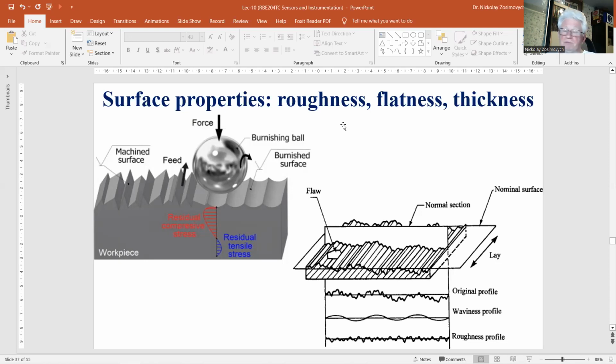Since the triangulation principle allows contact-free distance measurement, it is preeminently suitable for measuring objects having a high temperature. An example of this application is a system described for measuring the flatness of hot steel plates after being pressed by a roll. In the application, a light strip is projected under an angle of 30 degrees onto the sheet, moving at a maximum speed of 15 meters per second.